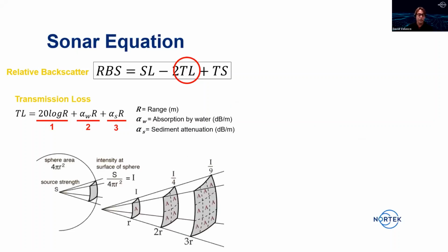Now, geometric spreading, as you have probably already heard or seen an illustration similar to this one, means that the signal gets diluted with the distance from the instrument. And so that needs to be corrected so that the intensity of the signal is independent of how far away the measurement volume actually is. These alpha terms over here are the attenuation coefficients, both for the water and for the sediment itself. Now, these can be modeled, but in practice, they're probably best estimated from actual measurements themselves.